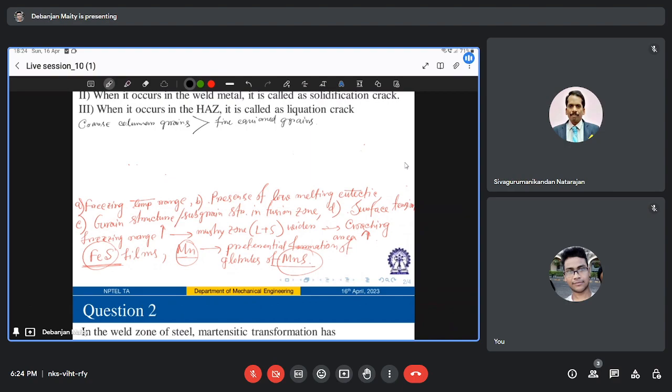Thirdly, when grain boundaries are greater, the concentration of potentially harmful low melting point segregates is reduced, hopefully to below some threshold that causes cracking. And besides these effects, the head-on impingement of columnar dendrites growing from opposite sides of a weld can lead to severe centerline segregation, right? And yeah, this is a particular problem in austenitic stainless steels, as I was mentioning.